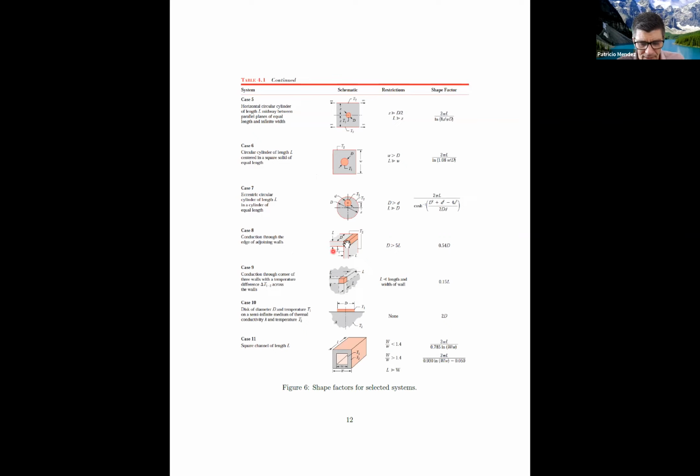Look at this. This is an edge. So let's say you want to calculate heat losses in a cooler, and the cooler is made of thick styrofoam. You can assume the styrofoam is so thin that we don't need to worry about the edges. But let's say you want to do an extra good job. So let's say that the styrofoam is thick and each of these sides acts as a wall, and we know very well how to work with the wall. And the edges are going to have their own heat transfer coefficient. We know how to do it now because somebody did the calculation for this very complex problem of the edge.